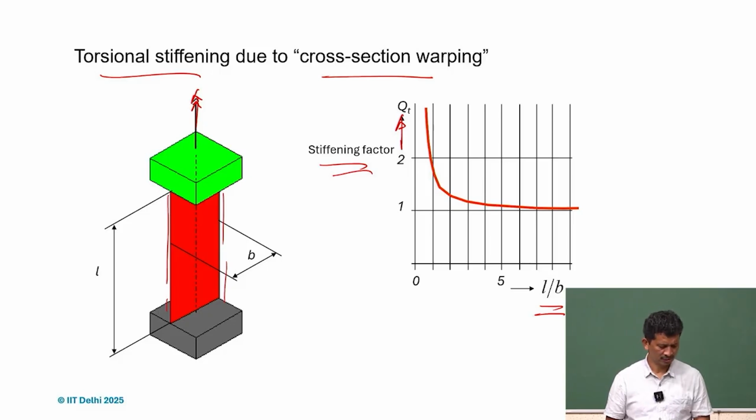It means the outer edges will get stretched, and the inner part, the axis, will get compressed. So they will start fighting, and definitely because of that, since there is a huge compressive load, there will be warpage. It's also a kind of buckling phenomenon, and we cannot use it anymore. So this deflection is very limited.